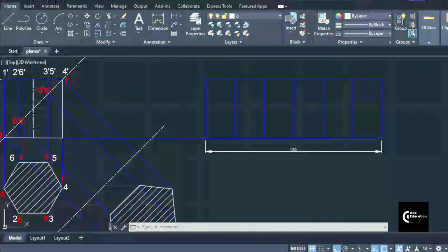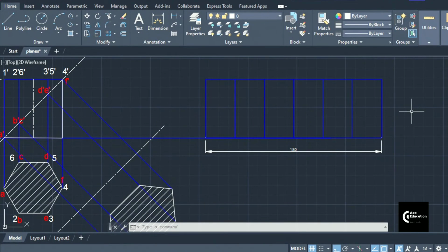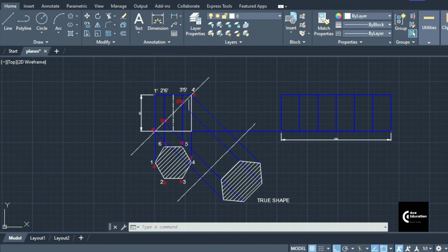Now friends, this is what we have drawn, the developed surface in the projection layer, because we want to show only the retaining part of the solid. The removed part should not be shown in the diagram. So that can be shown with the help of the projection layer only. So we'll try to project all these points of the section on this developed surface.